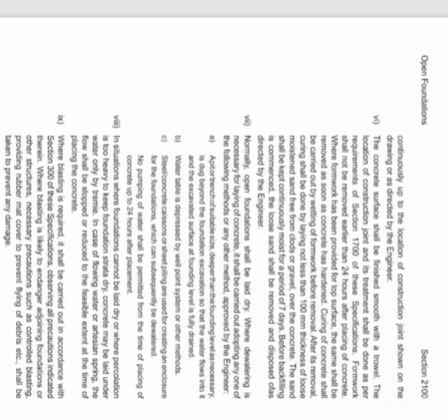In case of flowing water or a certain spring, the flow shall be stopped or reduced to the feasible extent at the time of placing of concrete.